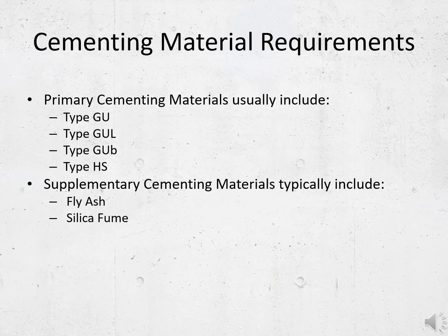Cementing materials test documents should be current and readily available for inspection by the auditor. Test reports should show each material's compliance to CSA standards and should be reported by a lab certified to CCRL or AASHTO. The list of materials presented here is historically what's been used in the Alberta market.